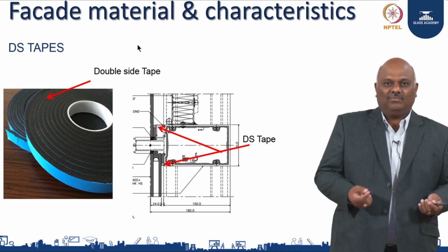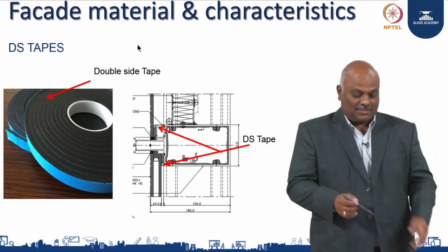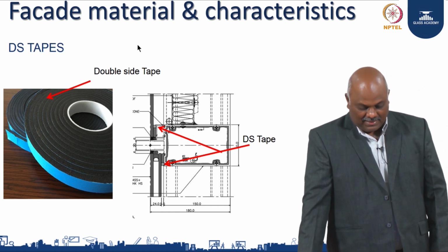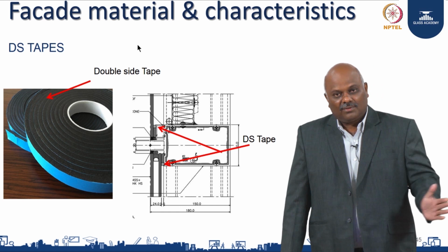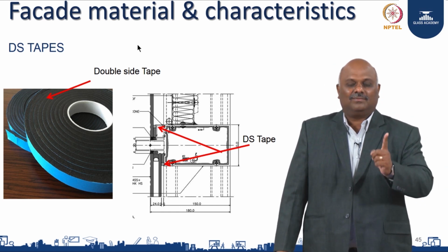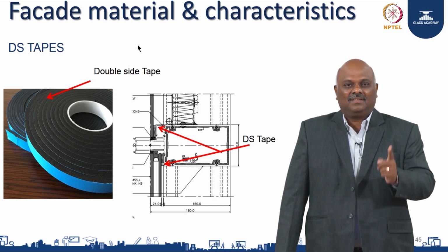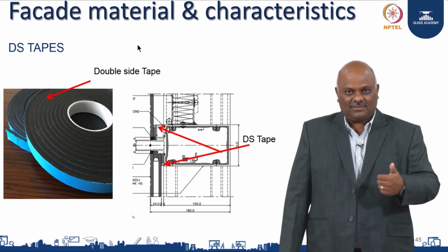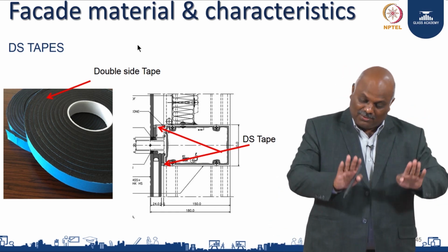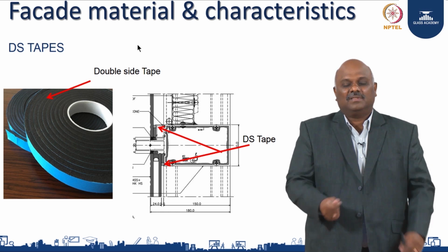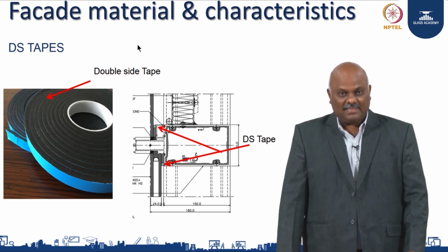A foam tape which has glue on both sides, that is all, simple. You put this tape in this place and then you glue the glass, so that the space you created is for the glue. So, you create a space required for the sealant to travel. So, you put the double side tape and then you glue the glass to the frame, temporarily holding it there. Then what happens? You are ready to apply a sealant.